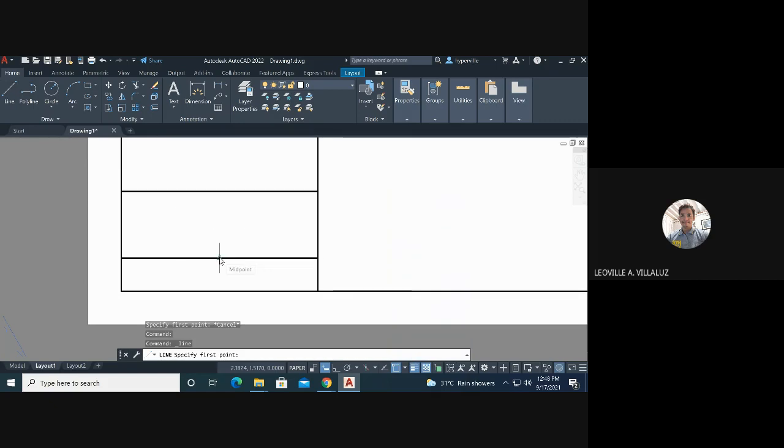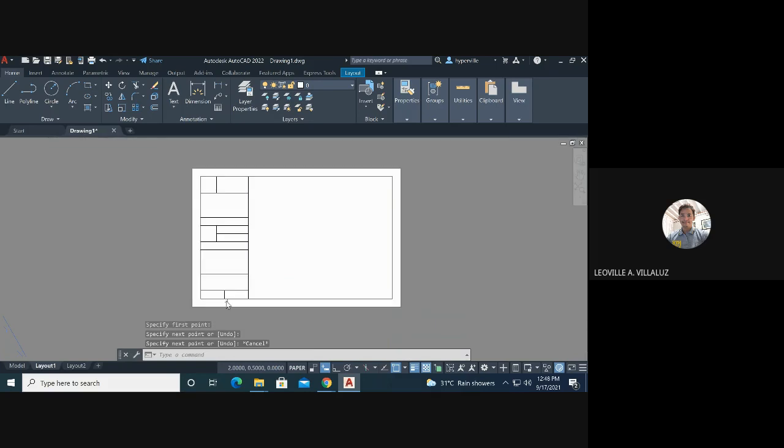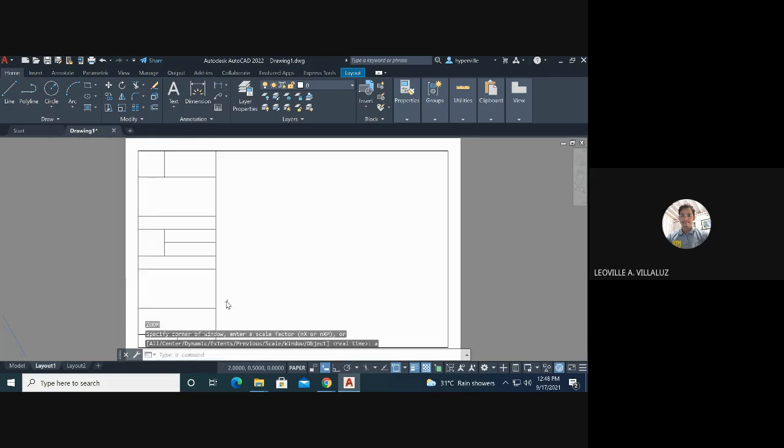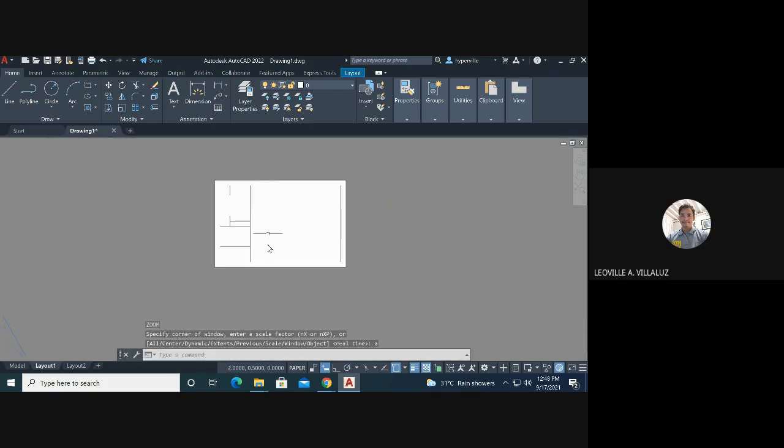Okay, as you remember the symbol, if triangle it is midpoint, if square it is endpoint. If the symbol is like, as we started, click and drag at the bottom. As you can see, there's an angle, 90 degree, this is perpendicular, and click. And escape to unhold the command.